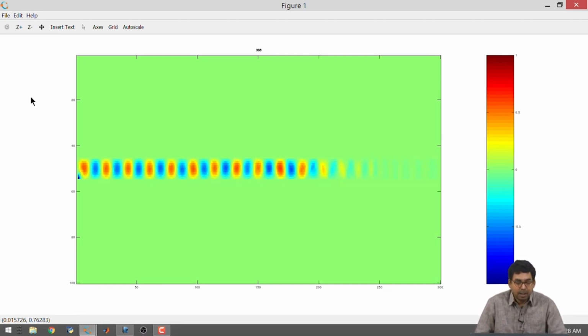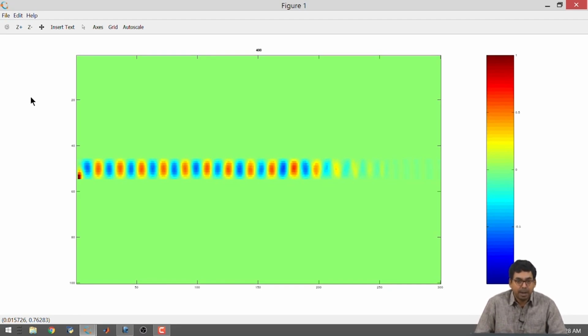So, it tells us that in practice, if you want to excite multiple modes, you could do that with a point source placed in different locations in this waveguide. Maybe if you placed it exactly symmetric, you will get some kind of pattern, but if you moved it towards one plate or the other plate, you may excite the other modes. So, we always have this question: what do multiple modes mean and how do I excite these modes?